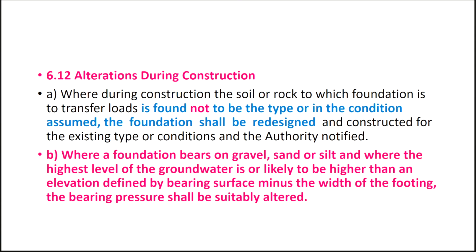Yes. So you must be aware, from whatever you have learned in your academics also, that when water is in that particular range, there is something called saturation of that water, or it will be in a submerged condition. So in submerged condition, there is an uplift force and your net weight will be reduced. So in that case, as you must have seen, normally it reduces by 50%. So you have to redesign that.